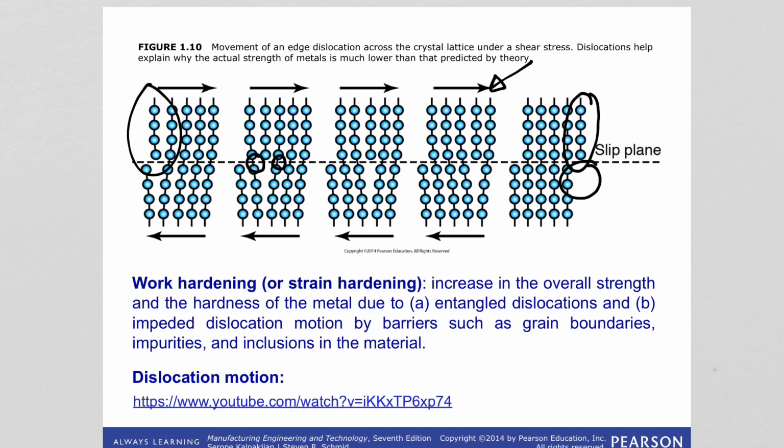So we have millions of dislocations inside. Of course, this is just an atomic scale change in shape, but millions of dislocations move at the same time, causing a macroscopic structural change, the deformation that we see outside the material. We can see that, right? What is going on inside is actually the dislocations are moving.